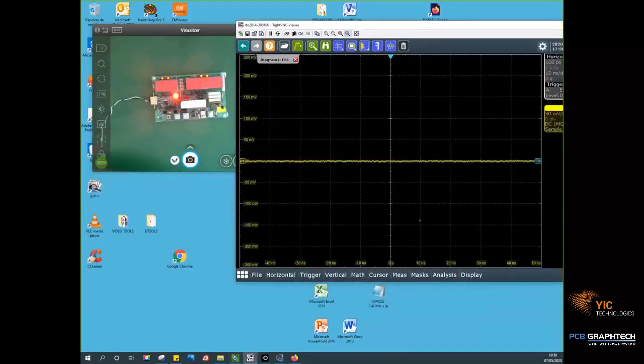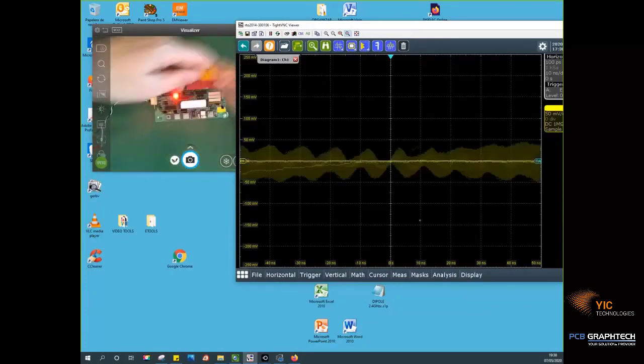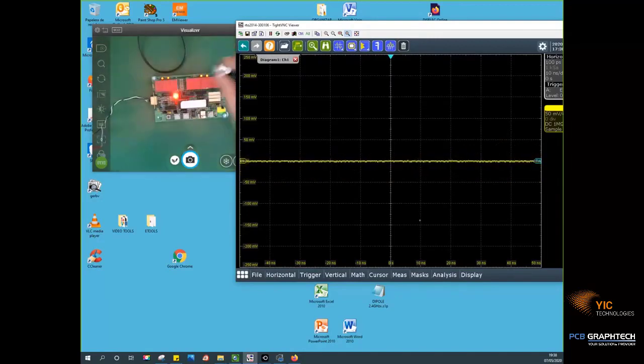So when I connect with a coax cable, let me connect to channel number 1. And let me connect in this way with the adapter. I have an adapter here. I connect the near-field probe. Then, when I go close to the circuit, I am able to identify where I have activity.